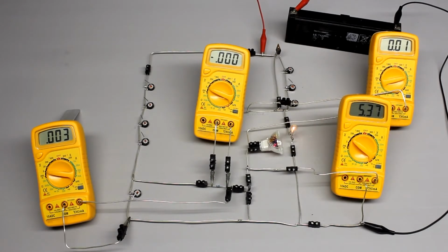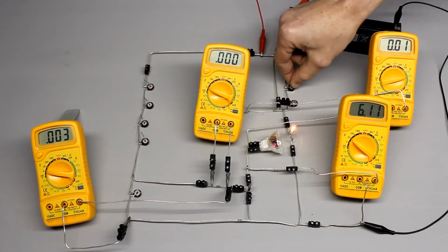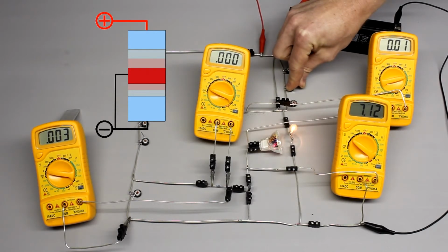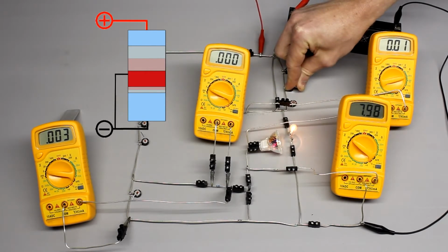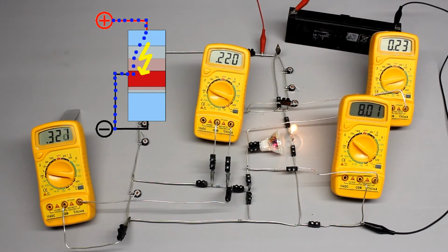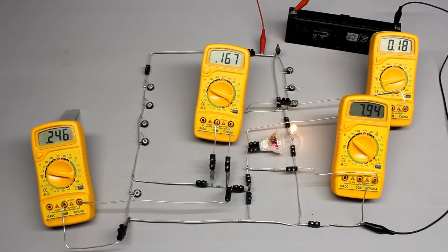This arrangement is called reverse mode. While increasing the voltage at the emitter-collector line without a base voltage attached to the transistor, the device becomes conductive near a voltage of approximately 8 volts. A current of approximately 20 mA is running through the emitter of the transistor. Also, a base current of 20 mA can be recognized, which is running contrary to the normal direction.